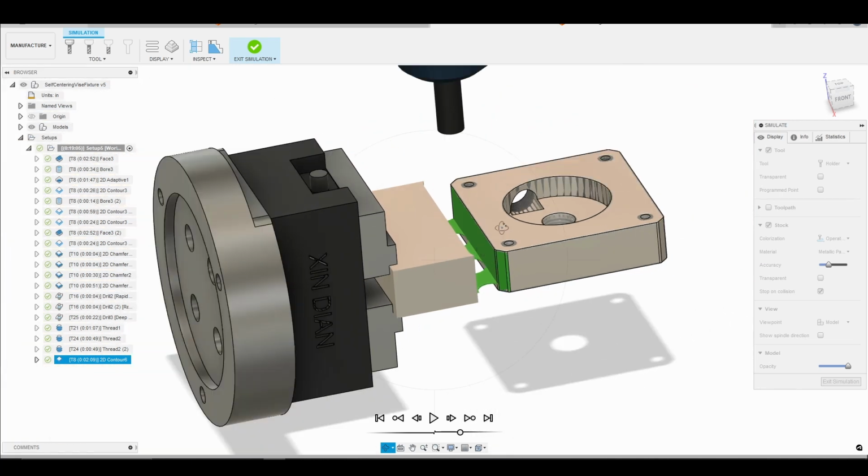Again, what I did is I just put it in a vise and then did a contour using the conversational and Path Pilot and just took off 5 thousandths, and that cleaned up the back side of the part for me.